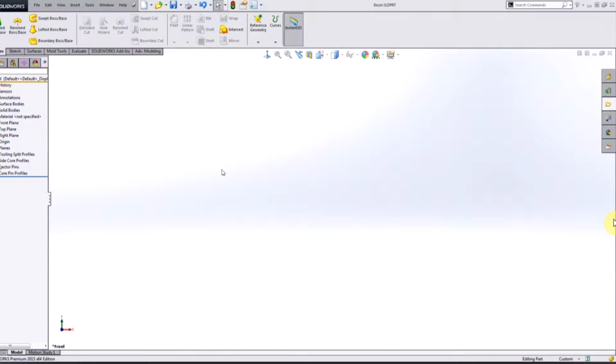Whenever I'm creating a mold or the cavities for a mold, I need to be concerned with the model itself and also where it's coming from. We don't always have the luxury of designing our parts all in SOLIDWORKS. Sometimes we have to take in CAD files from other programs. So that's where we're going to start this example today, by taking in an IGES file and showing you how we can build that mold tool even if we get this body imported from another CAD program.